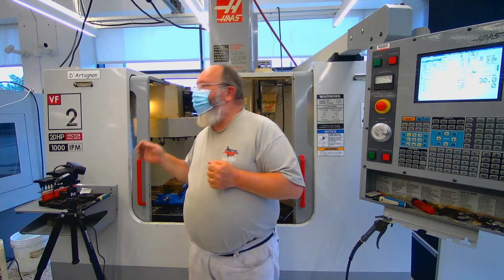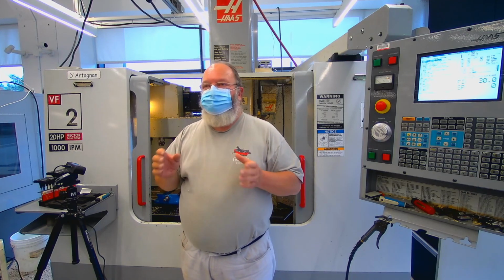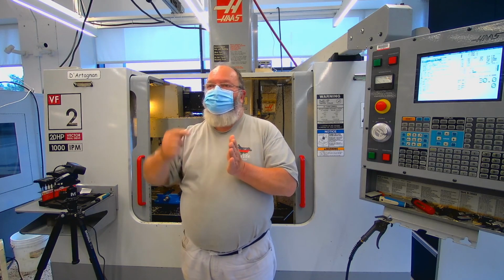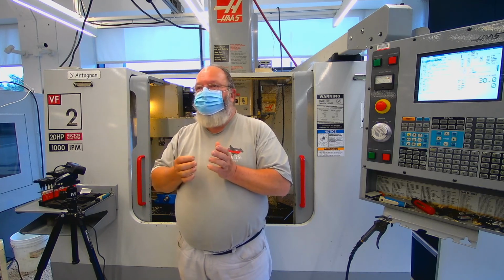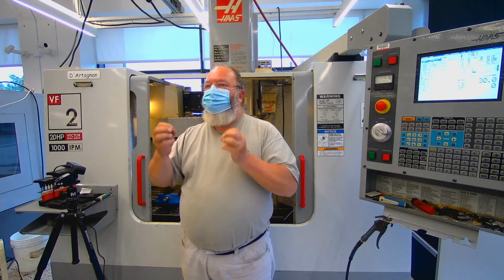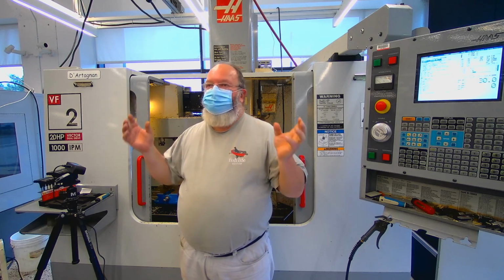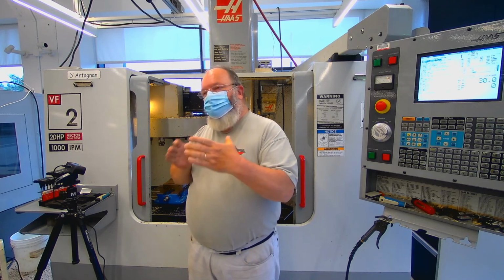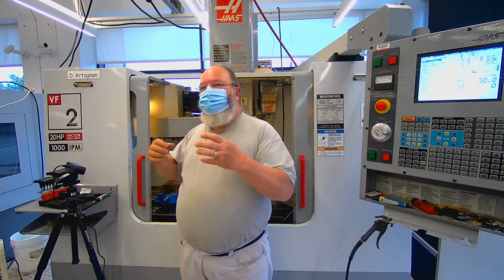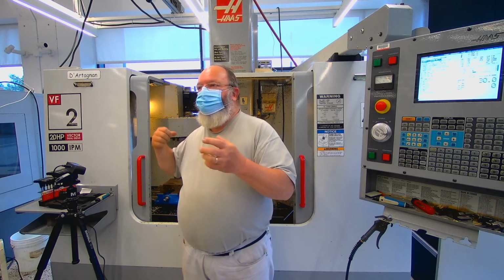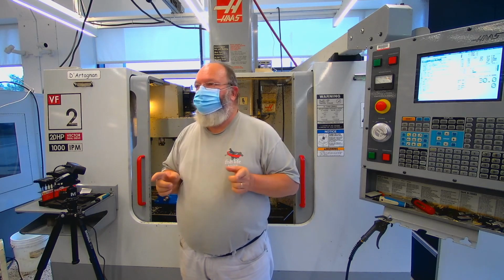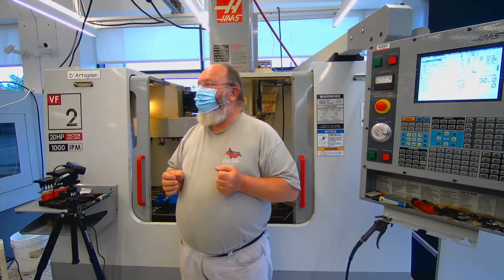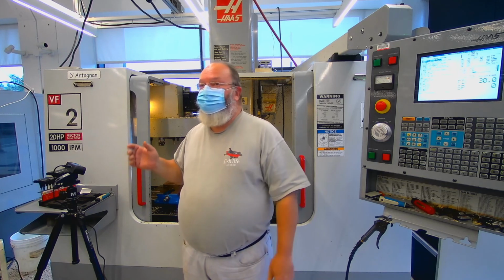The most impressive deburring thing I ever saw was a Y tube that was made for the medical industry, and it had to be welded. Well, when you weld on the outside of the tube, what you create on the inside are microvoids. That is the end of the world to the medical industry, because those are tiny little incubators. So they hooked us up to a machine, and they forced an abrasively impregnated clay through this tube for 3 hours. And when they took it out, it was an absolute miracle on the inside of the tube. But it's about the most expensive deburring operation I've